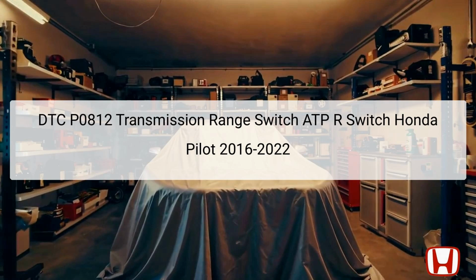The transmission range switch is crucial for indicating the position of the gear in the transmission to the powertrain control module, PCM. Incorrect signals from this switch can lead to erroneous transmission behavior, impacting vehicle operation. The error can lead to various performance issues as it affects both engine and transmission control systems. When dealing with this error code, a structured troubleshooting approach is critical for identifying and resolving the underlying issue effectively.